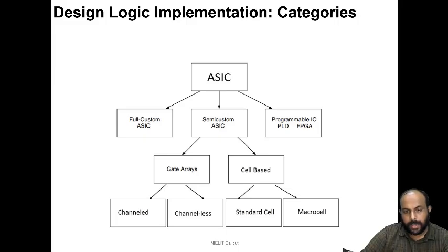Again, the semi-custom ASICs are classified as gate arrays as well as cell based. The gate array based semi-custom ASICs can be further classified as channeled gate arrays as well as channel-less gate arrays. Similarly, the cell-based semi-custom ASICs are further classified into standard cell ASICs as well as macro cell ASICs. We will see what all these mean and how they are different from each other before we start with the VLSI design flow.